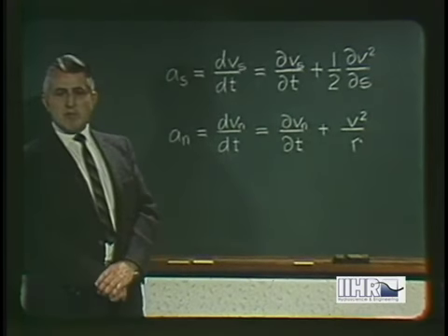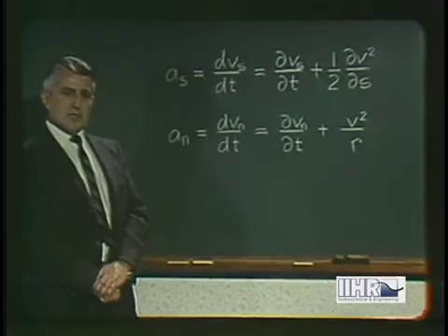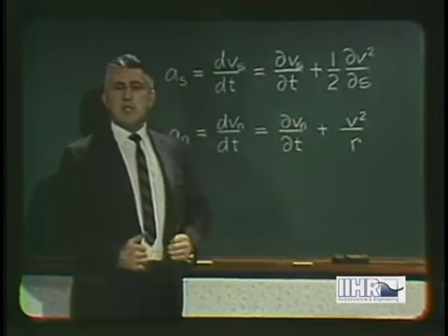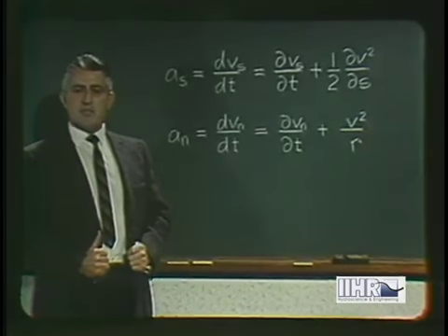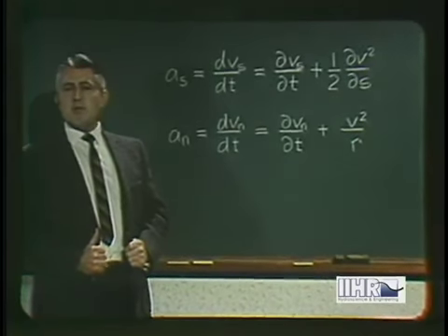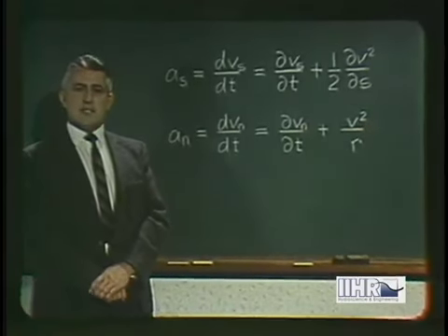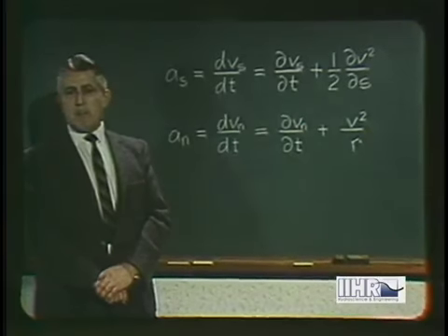If, by the principle of relative motion, an unsteady flow has been changed into a steady one, then the local terms become equal to zero and need no longer be considered. Obviously, a great simplification. It is possible, however, only if the flow takes place with constant relative velocity and without change in boundary form or orientation.